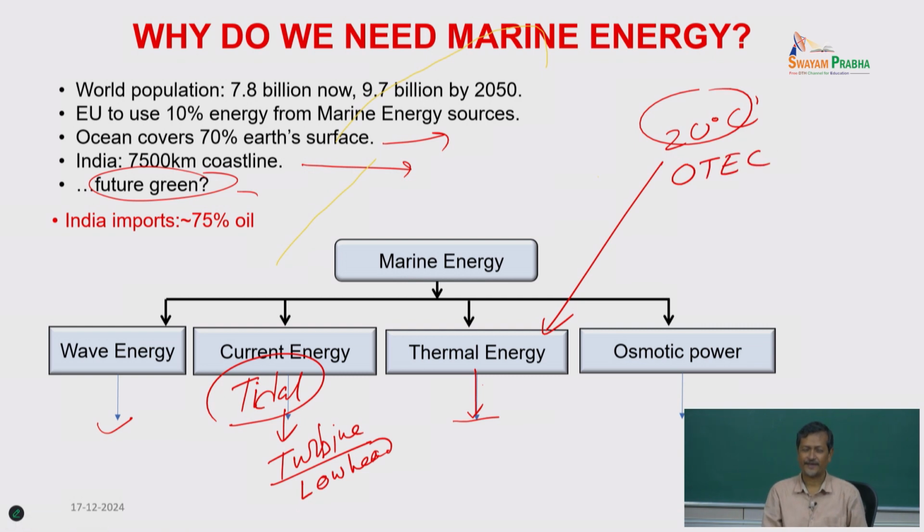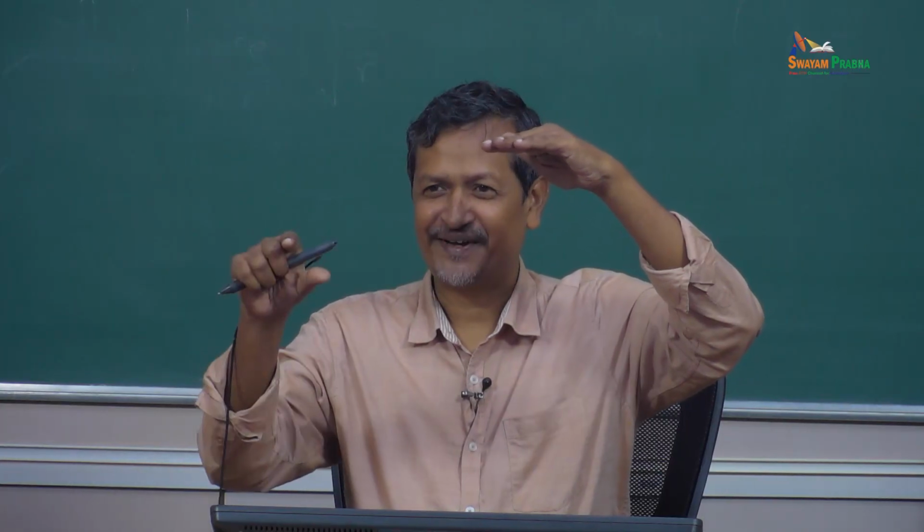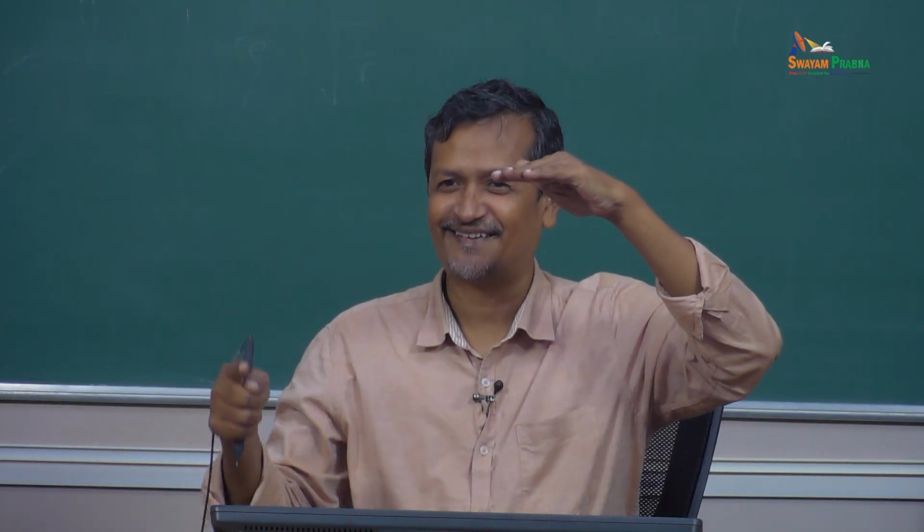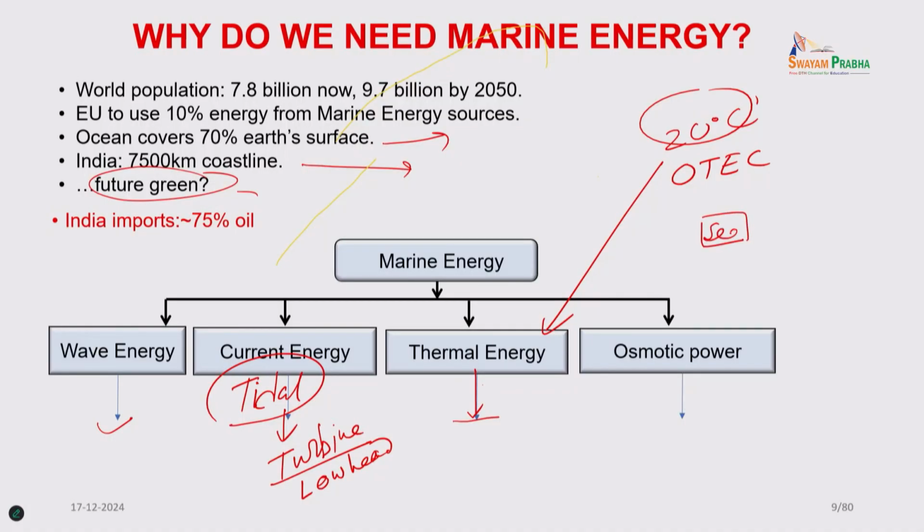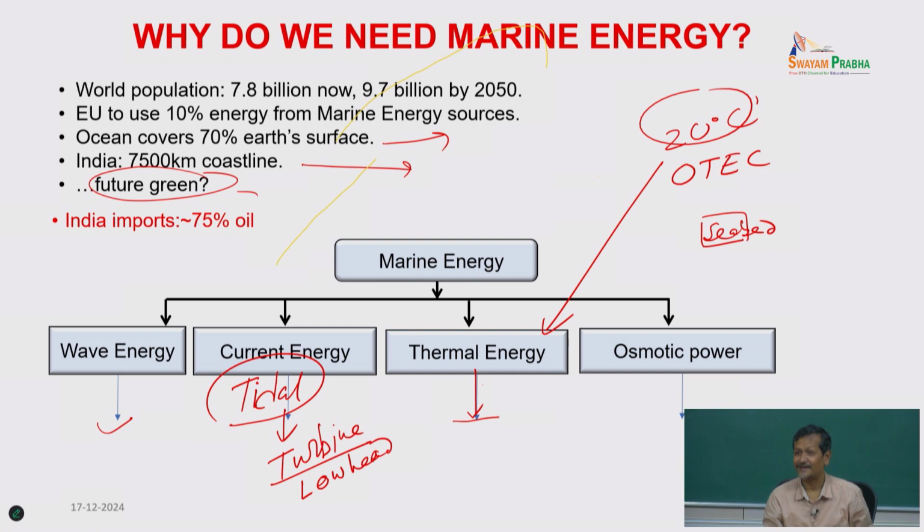So, how does it work? You have a low temperature, you have a high temperature, you create one ammonia loop, okay. At high temperature ammonia will boil, boiled ammonia, that is steam, you pass it through the turbine, at the bottom it will be cooled down, liquid ammonia, again it will become steam, turbine, the same Rankine cycle, okay. So seabed, so there condensation is happening, okay.